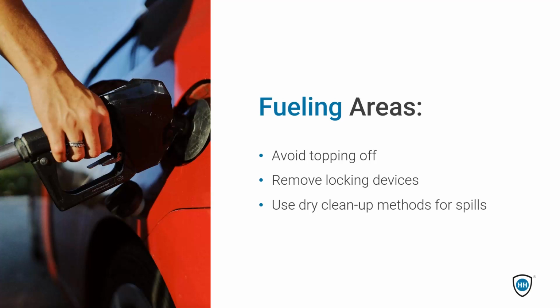That can be an absorbent pad, it might be loose absorbents, whatever you've got there to clean up the spills. Having that material readily available at the fuel dispensing area so that people are able to take care of it immediately and not just hosing that down to the nearest drain. These are all best management practices that we should be familiar with and will help us in those areas to prevent that release from getting into a drain.